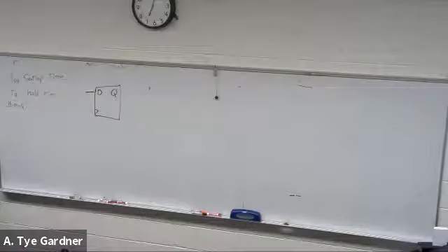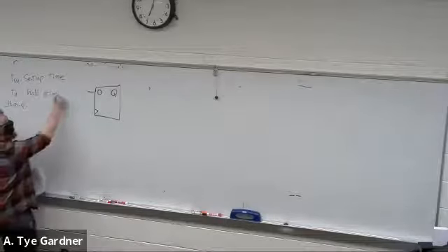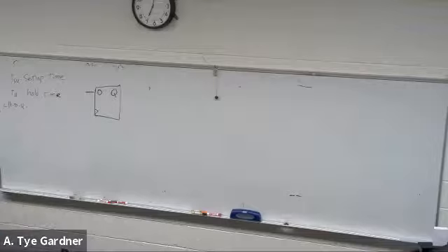It must be decided what it is for a certain amount of time before the clock rises. If I don't meet setup time, I can't guarantee what Q is going to be. Similarly, hold time is the amount of time I must stay the same after the rising edge of the clock.